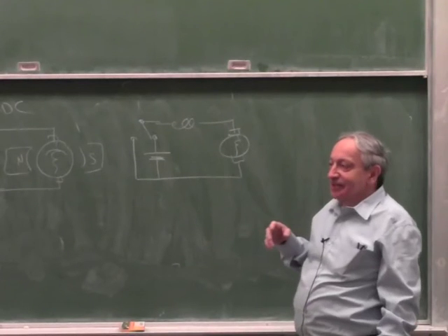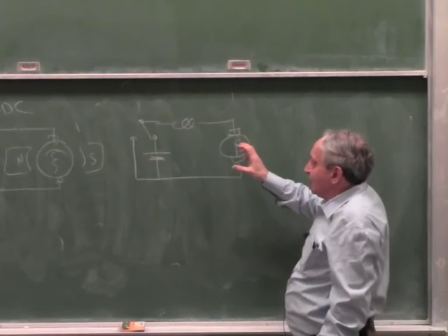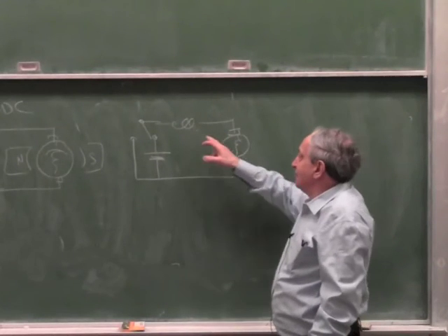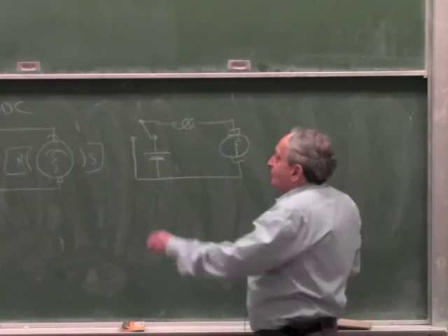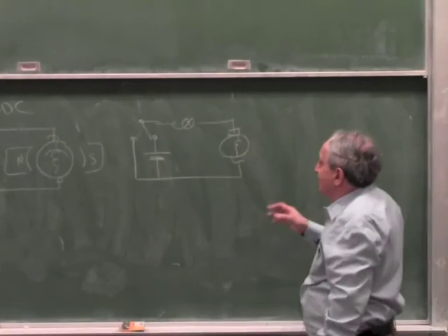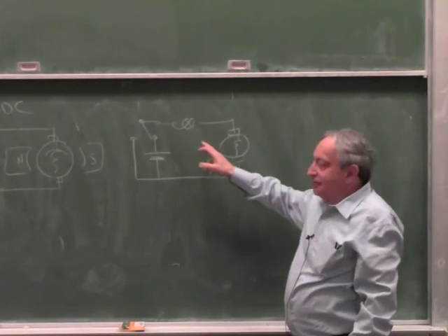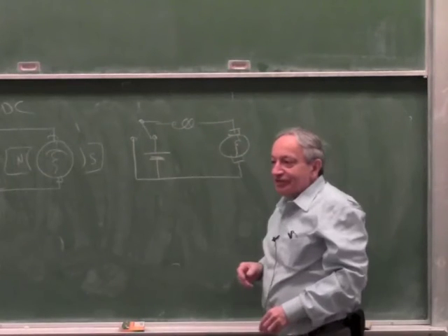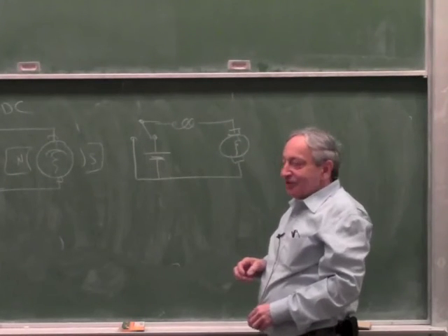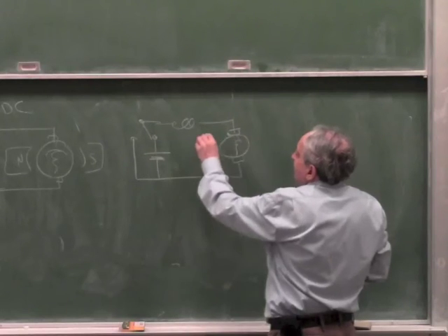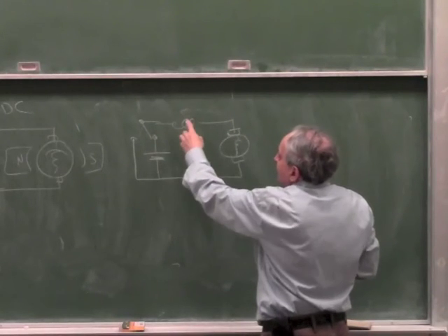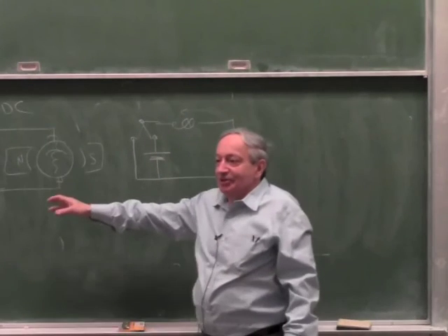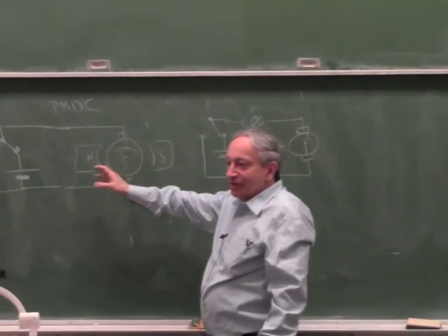The reason it does is at the moment you stop the current, there is still some magnetism, and also everything has a bit of residual magnetism. So when you switch it over, even if there was no current, there is a bit of residual magnetism. The residual magnetism starts creating a current, and the current increases the magnetic field. Okay? Because even if there was a little bit of magnetism left, a current will start flowing, the magnetic field will go up, and it will increase the current and still brake, but not brake as well as this. Because this starts braking at full torque right away.